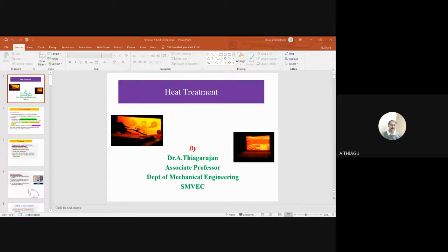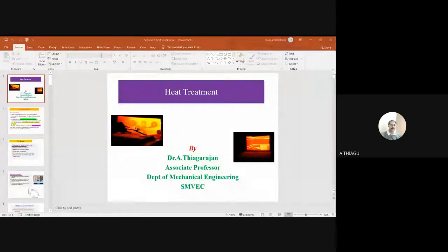It is called hardenability. The hardenability and the depth distribution of hardness are tested with the Jominy setup, which practically demonstrates how hardness is improved by the rapid cooling process. It is one of the very good setups where we can find this.